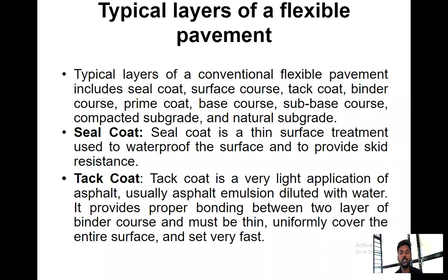Binding between the two layers of the binder course, it must be thin, uniformly cover the entire surface, and set very fast. Okay, it should be very thin and it should set fast. So seal coat is at the top to avoid water entering into the base. It acts as the waterproof layer and also provides the skid resistance. Tack coat is provided with the asphalt to give proper bonding between the two layers.